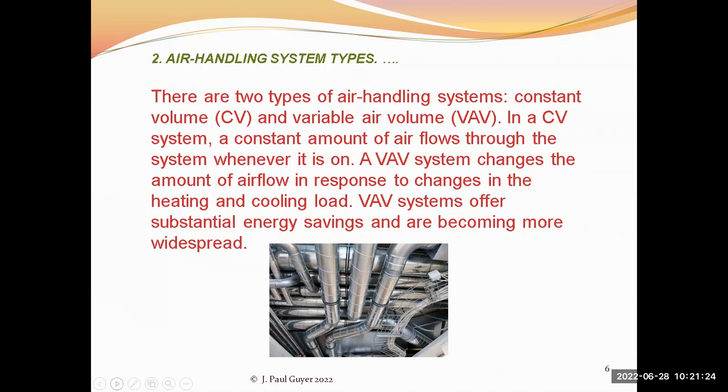But the fundamental drawback with constant volume systems is that there's only one thermostat. The only person that's happy on a floor, you might say, is the guy who's got the thermostat in his office, and he can set the temperature at whatever he likes, and that's fine for him. But everybody else on the floor doesn't have control over the temperature. So that's the big drawback of the constant volume systems, which are the old systems.